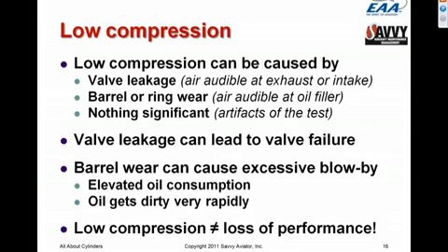They then pulled all the cylinders and they filed the ring gaps on the compression rings oversize to intentionally increase the amount of blow-by and to reduce the compression of the cylinders. And they filed those ring gaps to where the cylinders all read 60/80 in a compression test. They ran it up on the dyno, got precisely the same horsepower.